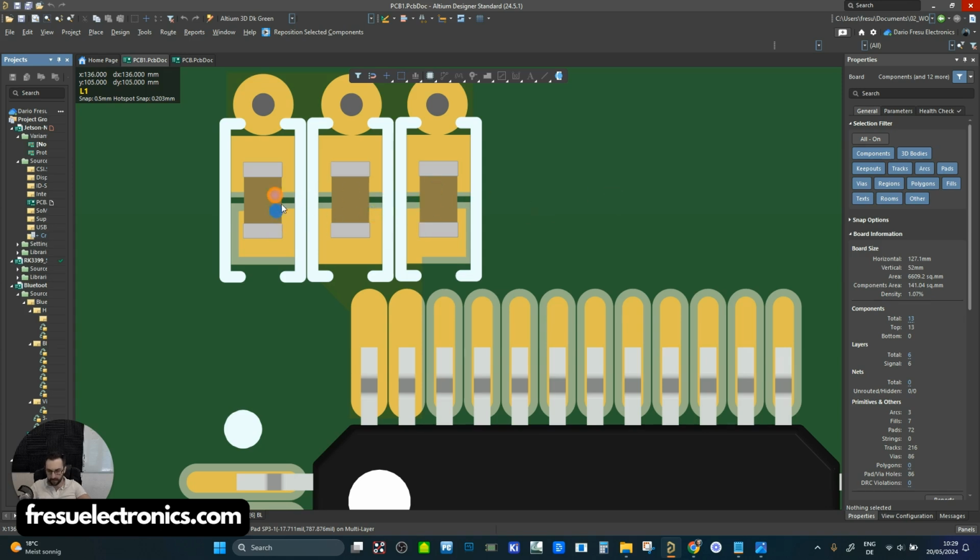Think about this: we have multiple capacitors with the same value, so the current is well distributed within these capacitors because it's the same current for each capacitor. But the capacitance is multiplied by the number of capacitors we're using in parallel, and the inductance is reduced because we're placing them in parallel. This is exactly the effect that we want. And so if we want to achieve a low impedance, these are the best strategies that we have.